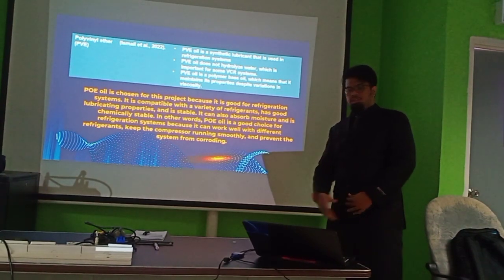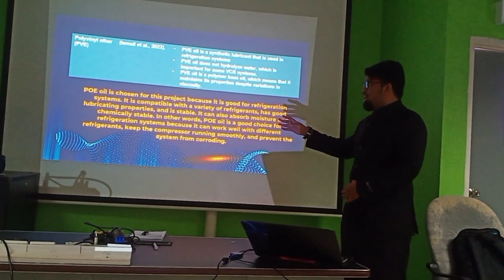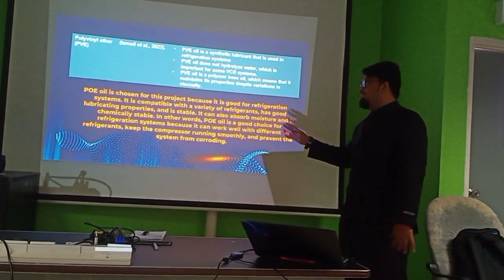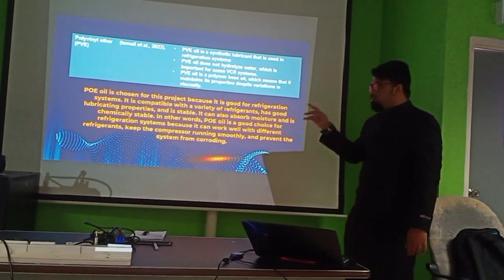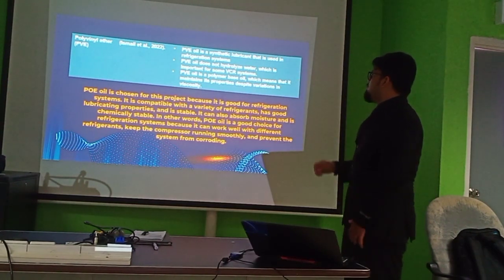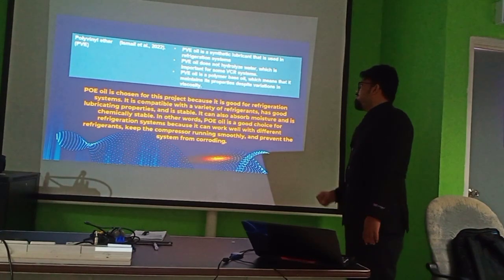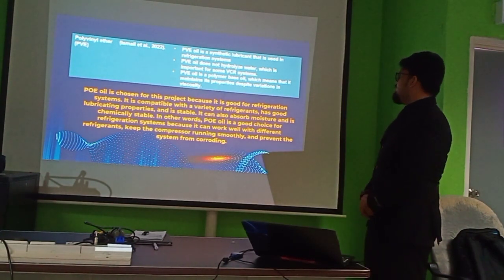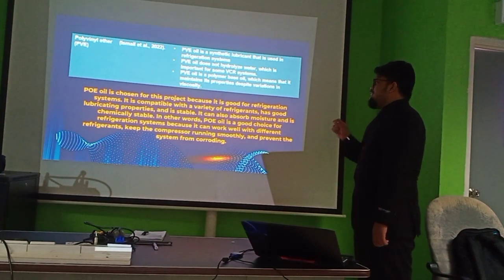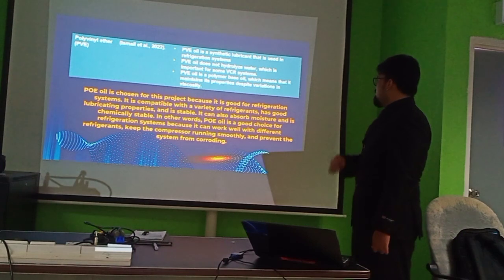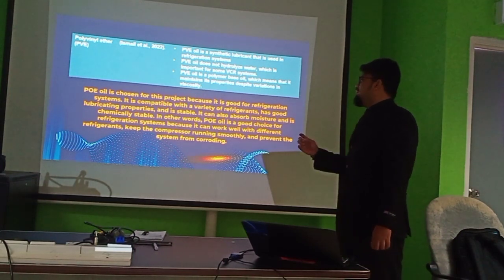So the summary of the compressor oil that I reviewed in the article or journal: based on this study, POE oil is chosen for this project because it is good for refrigeration systems. Plus, it is compatible with a variety of refrigerants, has good lubricating properties, and is stable. It can also absorb moisture and is chemically stable.